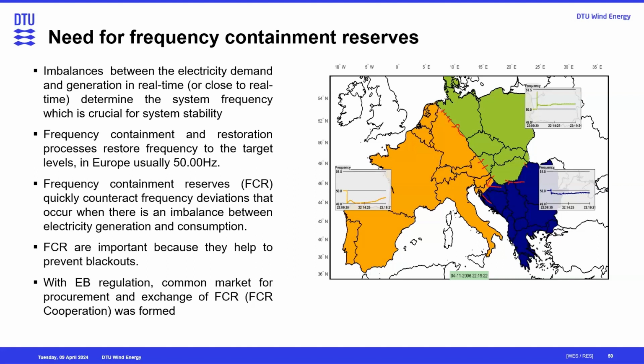They will stay connected, and with 50%, 60% capacity share in Denmark, Germany and Belgium, we might see a huge blackout in this region, because when the over frequency goes beyond a certain value, all the generators start disconnecting, and it will be quite time consuming, a few hours to a day, to bring the whole system back up.